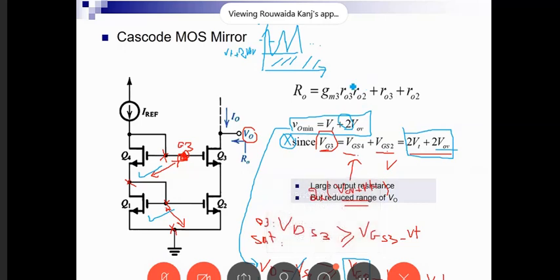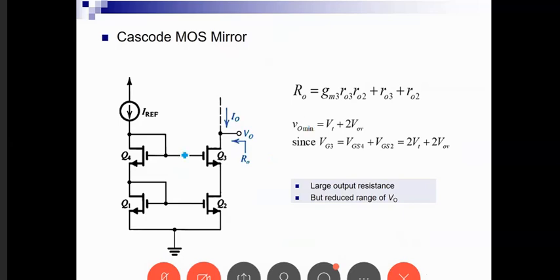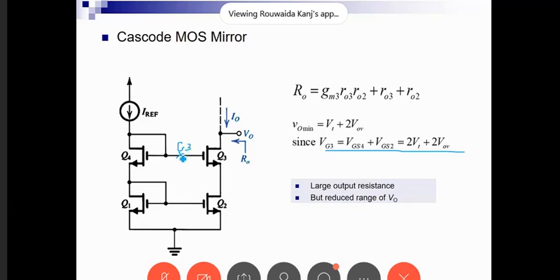Okay, so Ryan, I will repeat how we got the VO. Let me erase the ink. So what we said is that for VG3, did you catch, Ryan, that VG3 equals VT plus 2 VOV? Okay, so VG3 is equal to this gate 3. It is equal to VGS here. It is equal from this node to this node. It's equal VG3 to VG1 plus VG1 to ground. Okay, plus this to here.